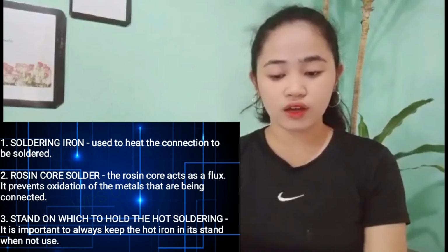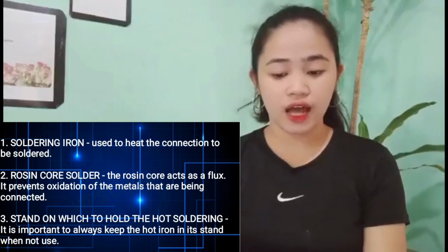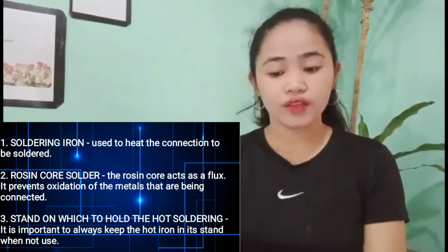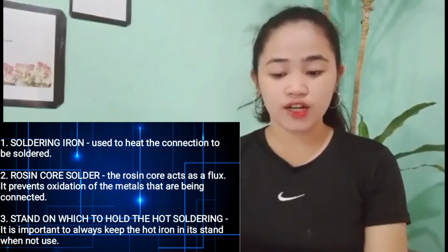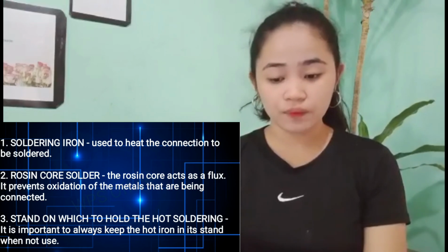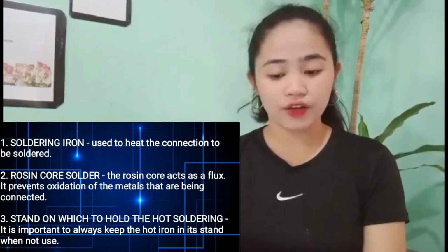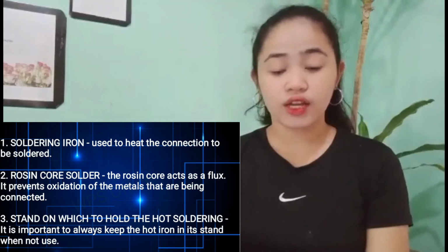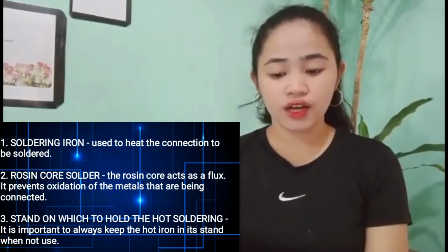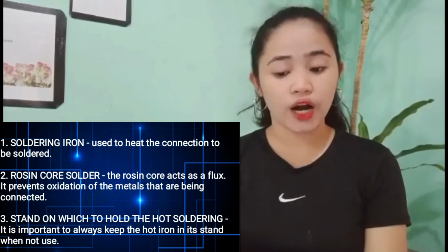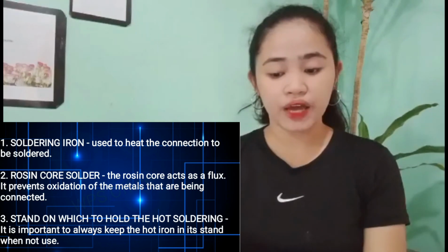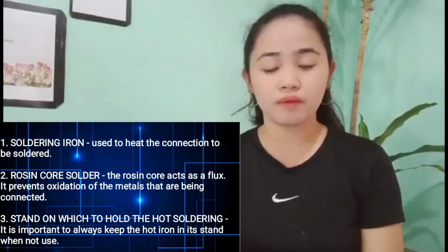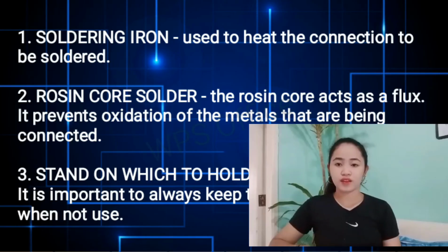Higher wattage soldering irons are not necessarily hotter. They are just able to heat larger components. A 40 watt soldering iron makes joints faster than a 25 watt soldering iron does. A soldering iron can be purchased at hardware stores and at most large department stores.